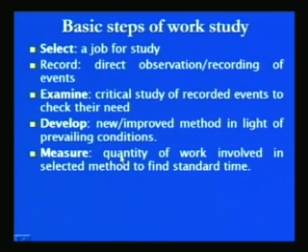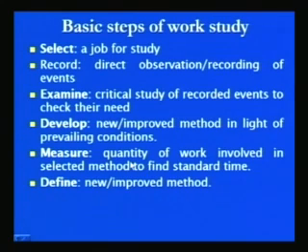Once the new method has been developed, it is quantified in terms of the work and the time involved for carrying out the job by the new method. This is called the fifth step, that is, measure, which basically involves quantification of the work involved in the selected method, and setting the standard of performance in terms of the time standard. Define is the next step, which is basically identifying and describing each and every detail of the new method regarding the material, machines, parameters, and the standard time allowed for carrying out the job by the new method. If these details are there, it will help to identify the improved method easily.